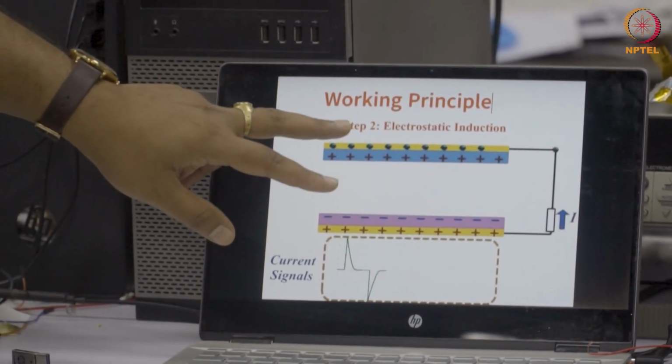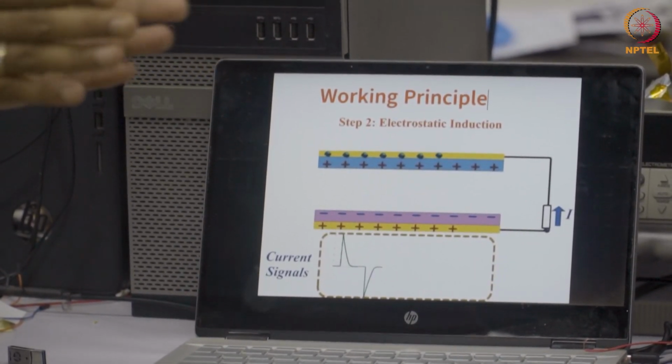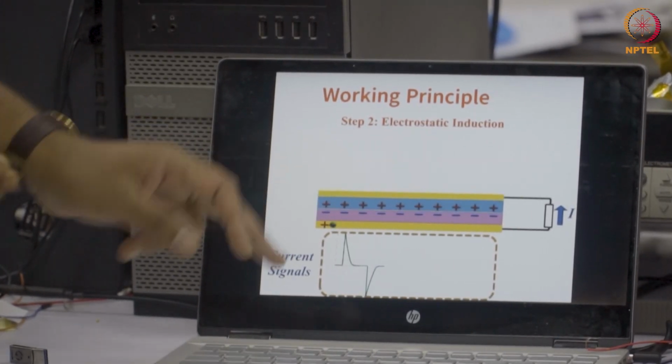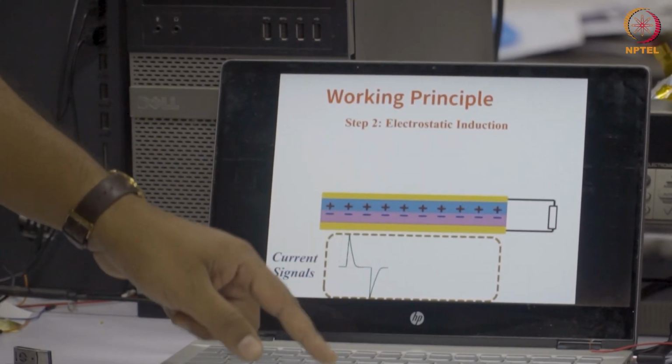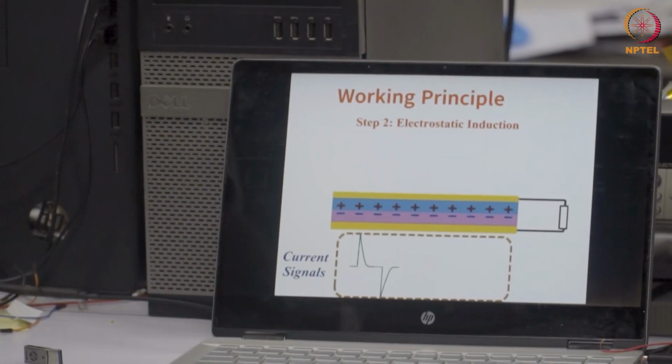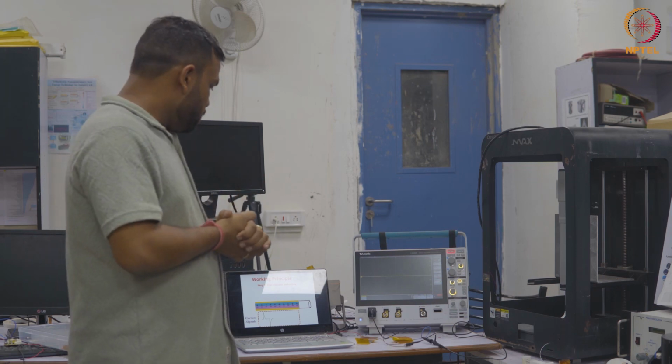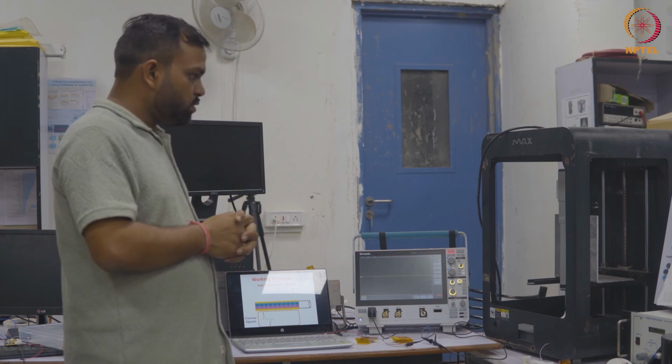Now it is going far from both the surfaces, and when it comes back again, the charge transfer between the positive surface and negative surface takes place again, so the negative cycle gets completed. With continuous contact and separation, we can get an AC output. This is one type of triboelectric nanogenerator, based on contact and separation mode. So this was the principle of triboelectric nanogenerators.